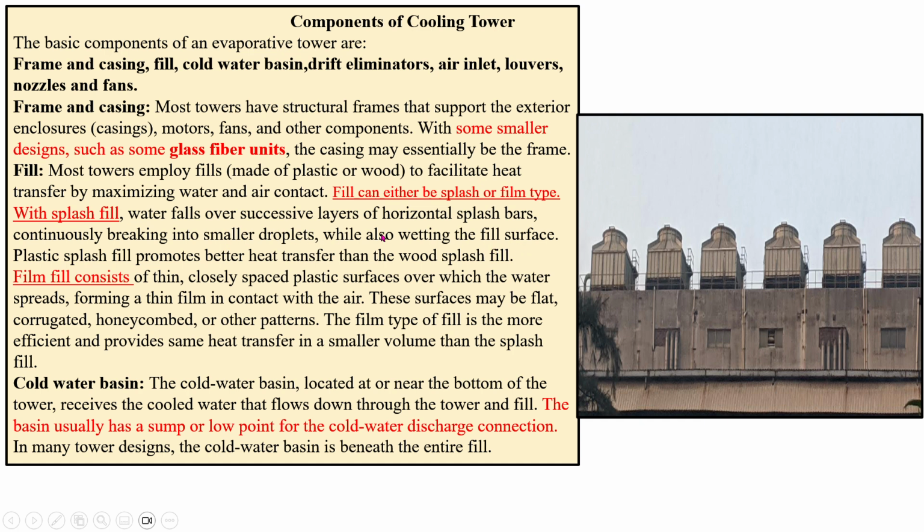So these are the horizontal splash bars where water continuously drops, and when the drop comes in contact with the horizontal splash bar, it breaks, and that promotes better heat transfer. Plastic splash fills promote better heat transfer than wood splash fills. If you compare wood splash fill with plastic splash fill, plastic gives better performance.